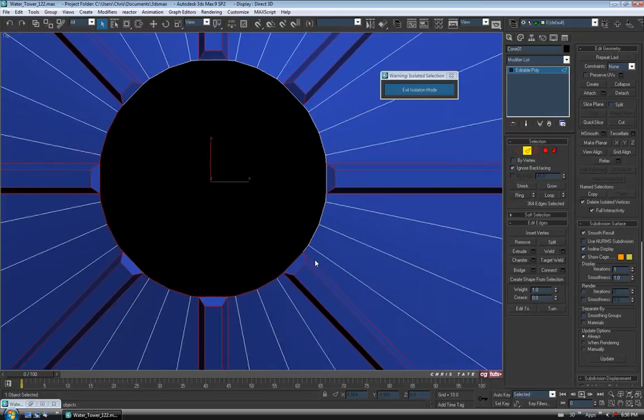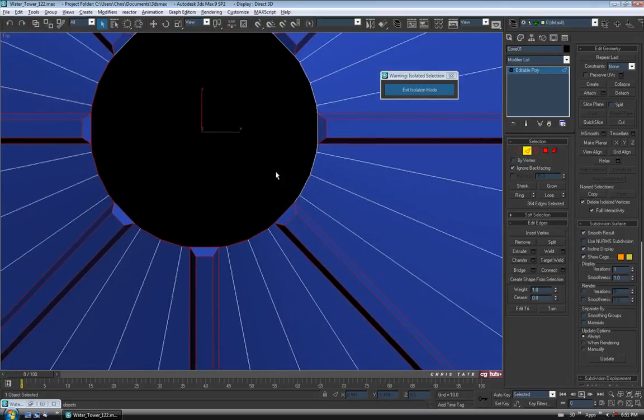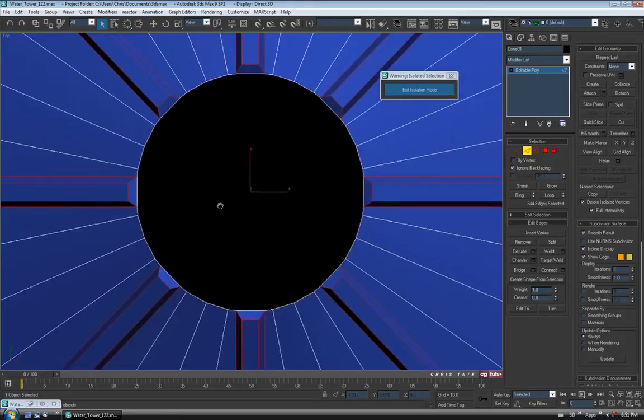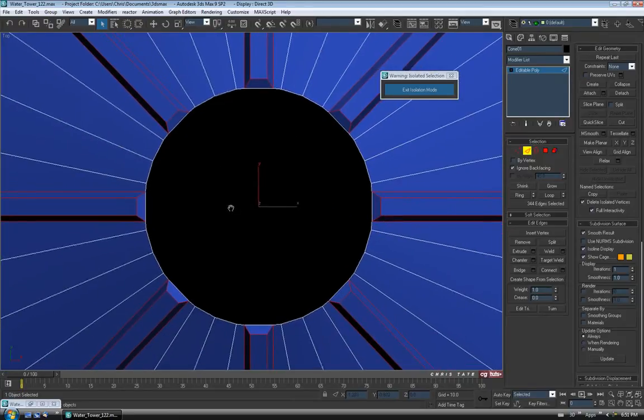If you want to make this a little quicker, you can always change your selection tool. If you left click and hold it down, you can change it to different things here. I'm just going to change to the bottom one, which is the paint brush. So when we hold Alt, we can just paint and deselect the edges, instead of dragging the marquee around them. Just carefully go. So just like that, nothing around the border is selected.